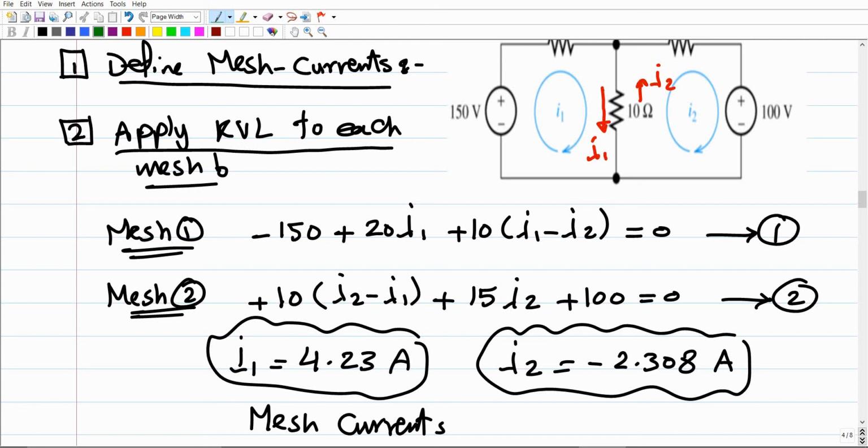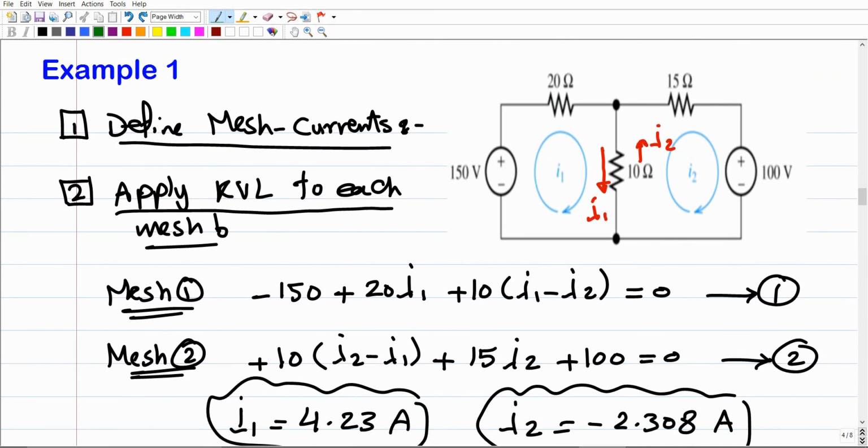It doesn't matter if you switch the direction of I1 and the same for I2, you're going to end up with the same result. So just pick any direction. Normally, for the loop voltage analysis using the Kirchhoff voltage law, we assume the clockwise direction, so you can follow the same procedure here, right?